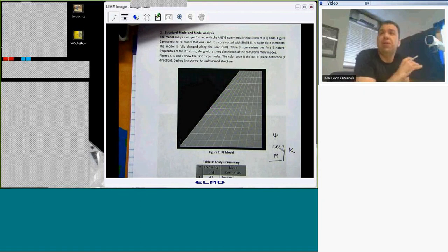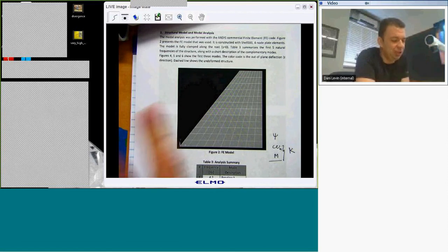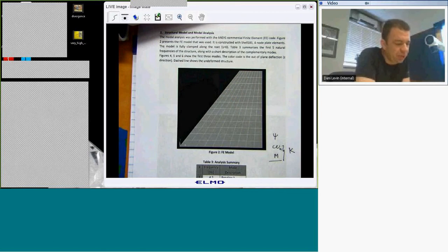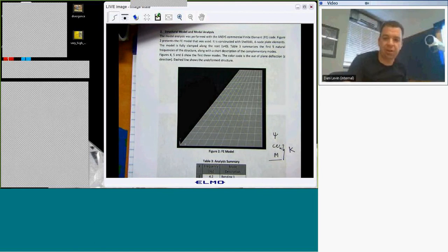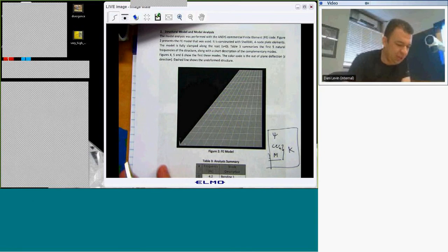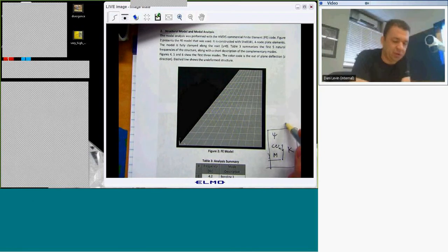In industry, every aeroelastic analysis is based on modal parameters. We are not putting inside the actual physical model. We are using the resultant model, which means that I need to provide to my aeroelastic software only these parameters, and that's it. The software doesn't care about the material, the boundary conditions. Everything is already here. Okay.